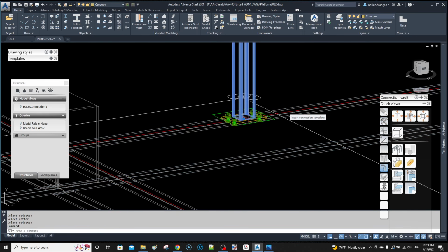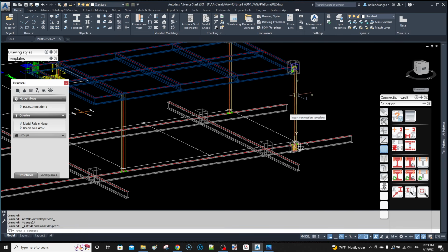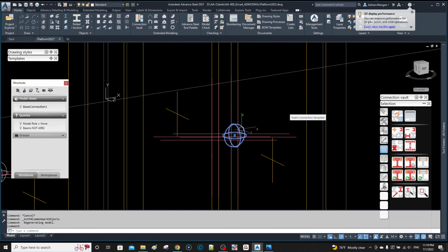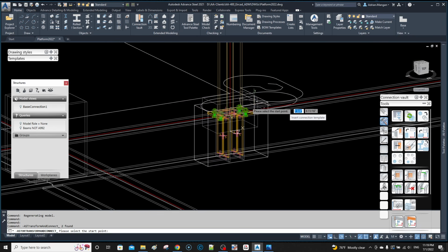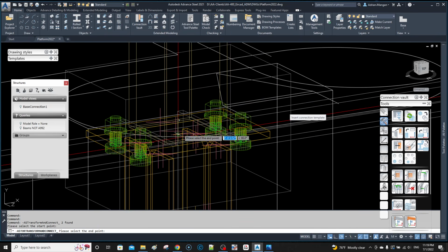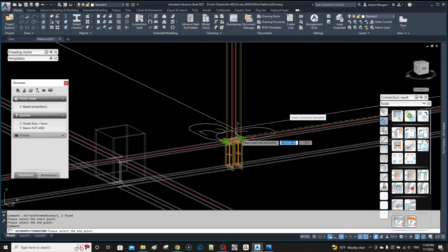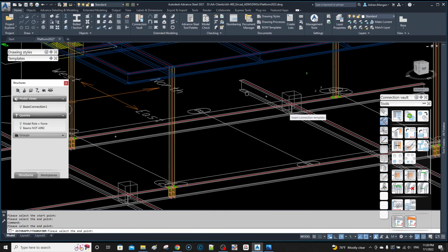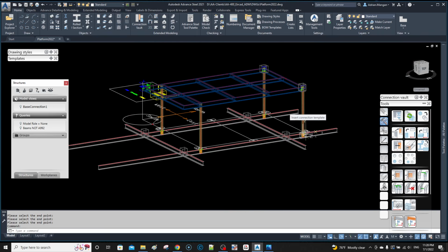Let's click on that column. Let's change it back to a square, and this red arrow here on the selection will deselect whatever you had selected or highlighted. So now we've got to copy the stiffeners, so let's just copy here and here, and let's copy here, and we can just do from the node of the column, and you can see it'll copy those in. So they'll all be standalone parts, because obviously they're existing beams.